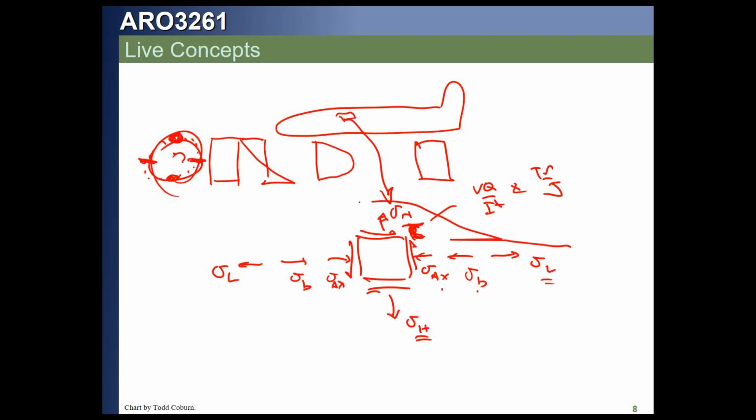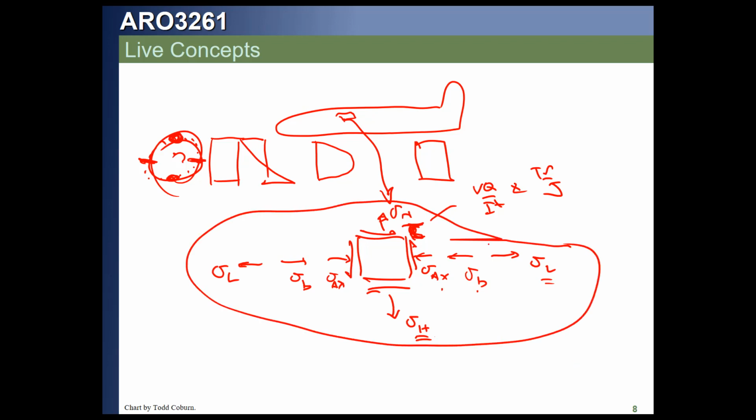While the hoop and longitudinal stress may have been plotted on Mohr's circle like this, there's our sigma, our hoop stress, there's our longitudinal stress, and that's our out of plane stress, giving us these little circles. The total stress state will actually have other stresses, such that the total normal stress on this X face is going to be the axial, bending, and longitudinal component combined. The stress on the Y face will be just the hoop component.